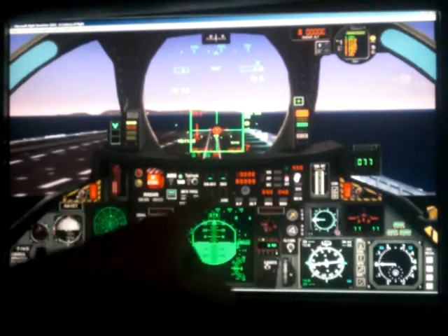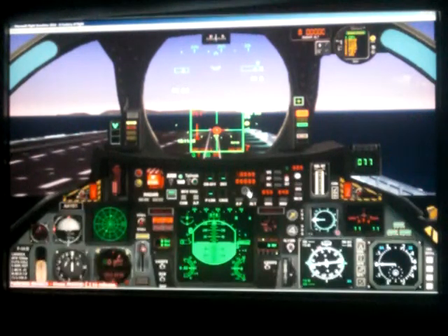And then same thing, vertical speed over here, altitude is right here. You have to click the knob to raise the altitude. There's 10,000 feet, and then there's your vertical speed adjustment knobs. A little dark, hard to see, but there it is. It functions like a trim wheel should, meaning back for putting up the nose, and then forward for pushing the nose down. So there's 2,000 positive vertical. So basically those are controlled.